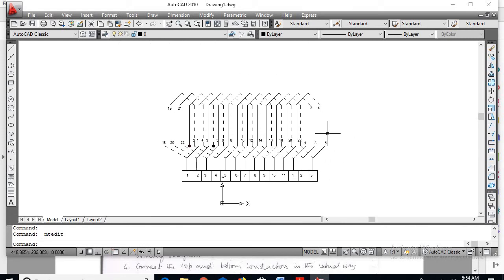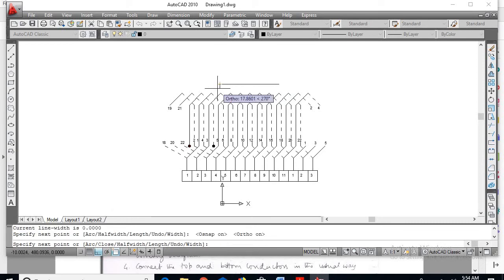So now let us go for the direction of rotation. Considering the generator, I'll go for polyline. Select the polyline. I'll switch on the ortho and object snap. Draw a line. Click here. I need the arrow, so go for width, W. Now it asks the starting width. I'll go for 20 as the starting width. Enter. Ending width, a sharp edge is required, so go for 0. Enter. So now the arrow is visible.